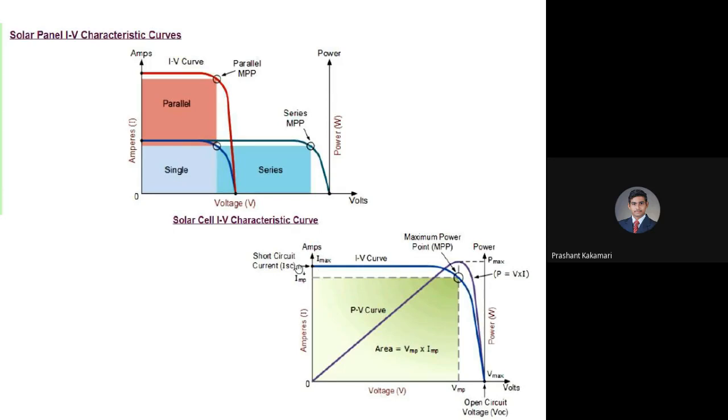And here, short circuit, that is once you connect both the wires, positive and negative, with the PV system, the maximum current that can pass once you short is Imax, which is shown here. So once these two points are available, at the optimum point in between, we are going to decide the maximum power point. That maximum power point is from the solar system.